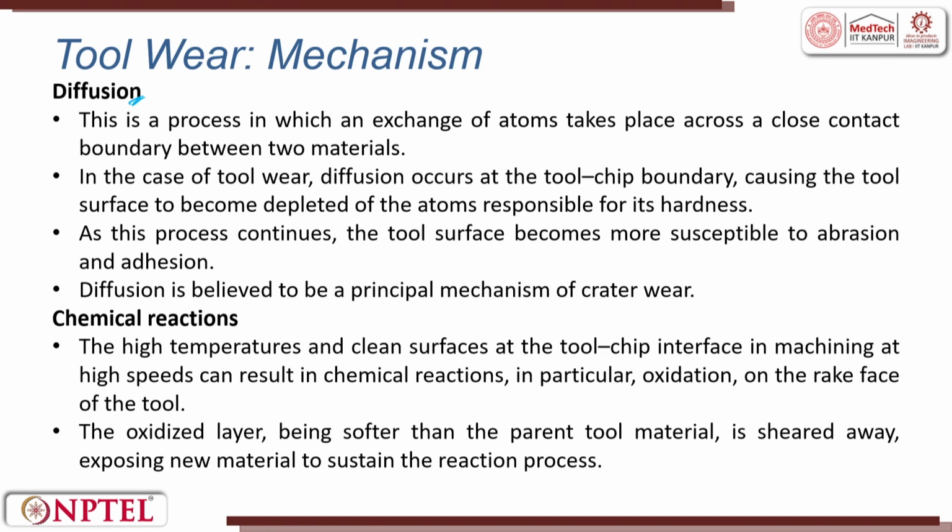Diffusion occurs when the temperature between the tool and the workpiece is very high. There is a transfer of atoms from the chip to the workpiece, and where there is a higher temperature, diffusion happens.